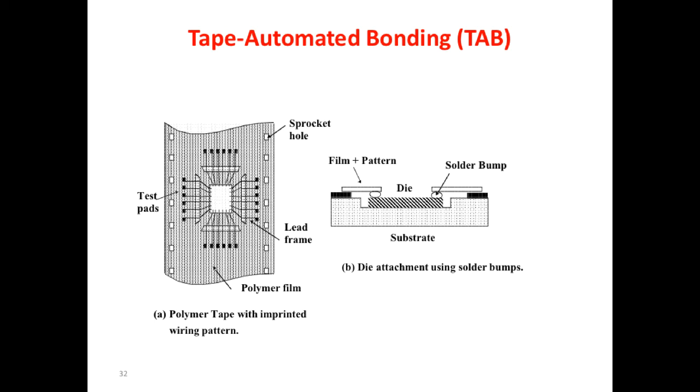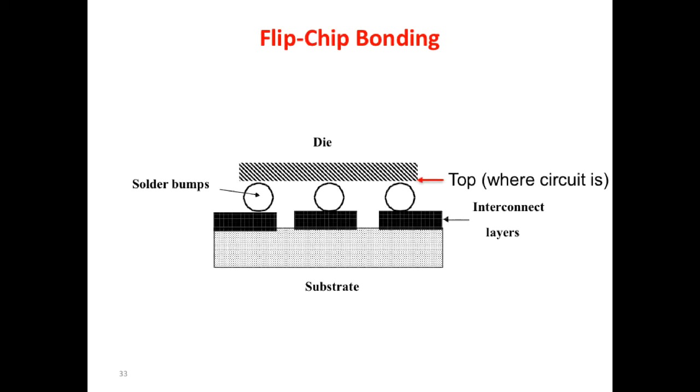Okay. From the point of view of the parasitics, there is a small difference because in this case the size of the wire can be tightly controlled. Also the geometry has been pre-done. It's not done every time. It's already prepared on the tape, so it is more or less under control.